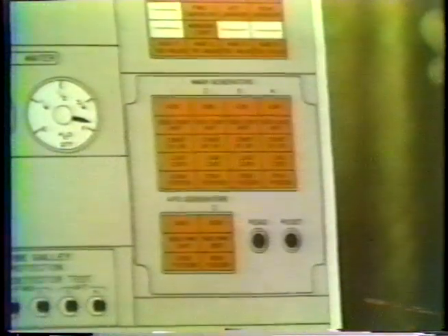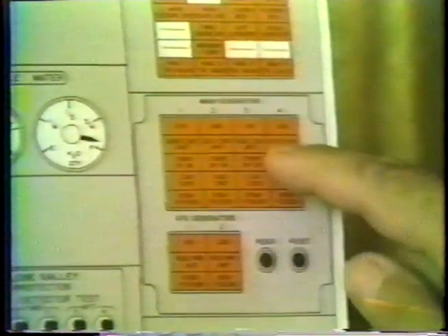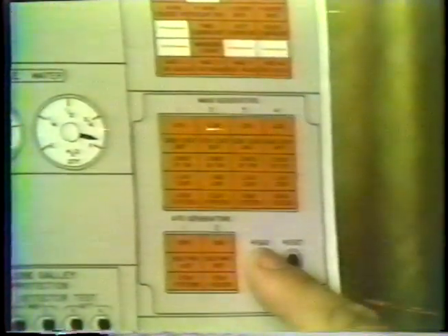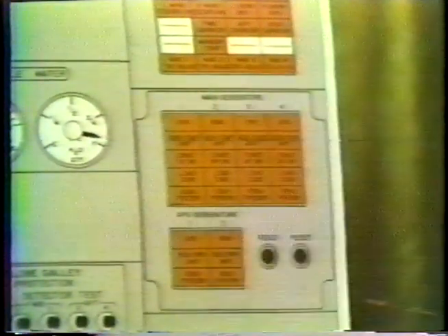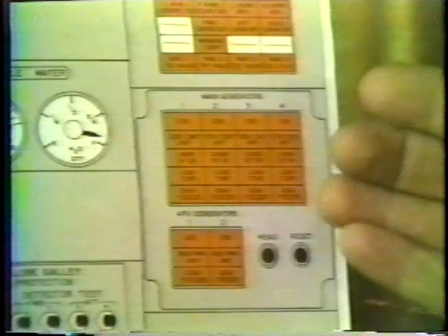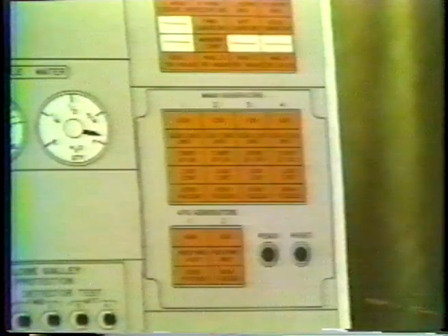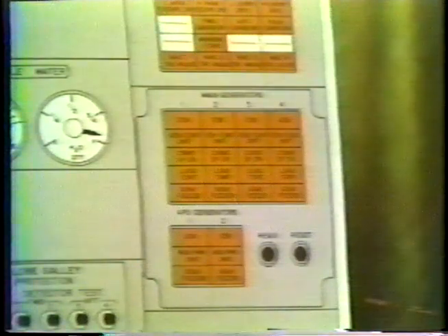One very important thing about this particular panel: no light will ever illuminate on this panel unless you're holding the read button. The read button must be depressed to indicate. Normally, flight crews do not erase the readings on these panels and leave them on for further troubleshooting by the mechanics that fix the problem.